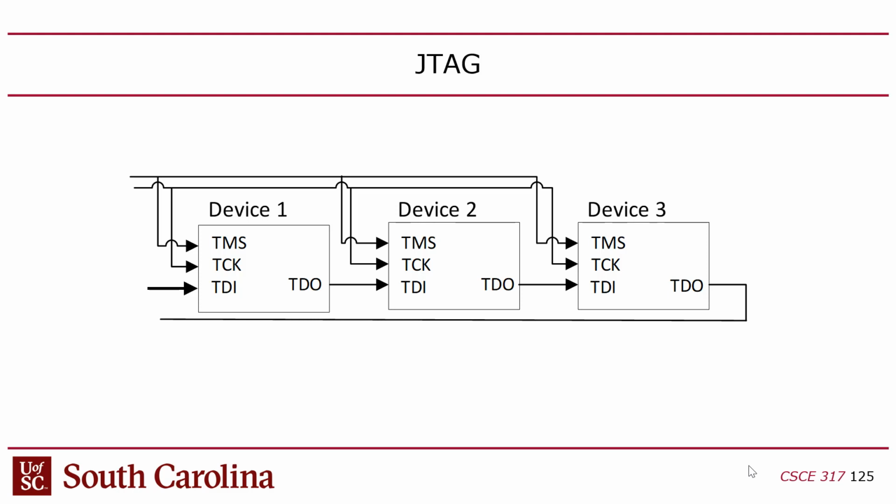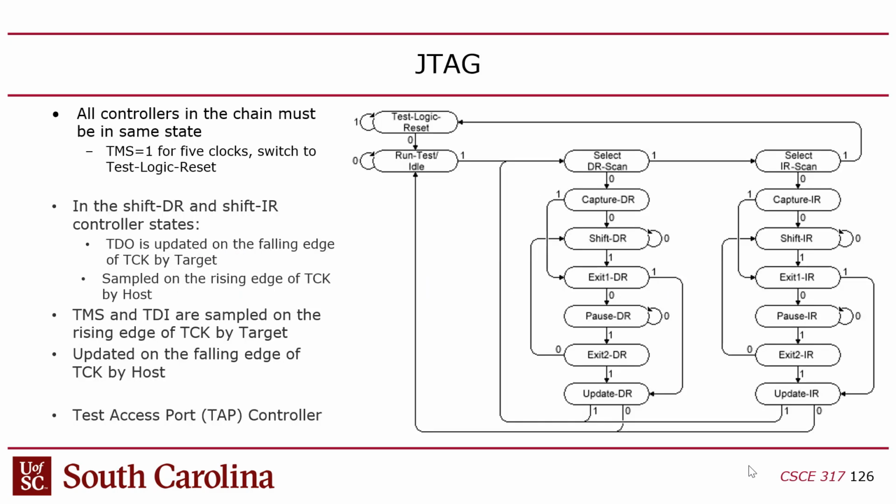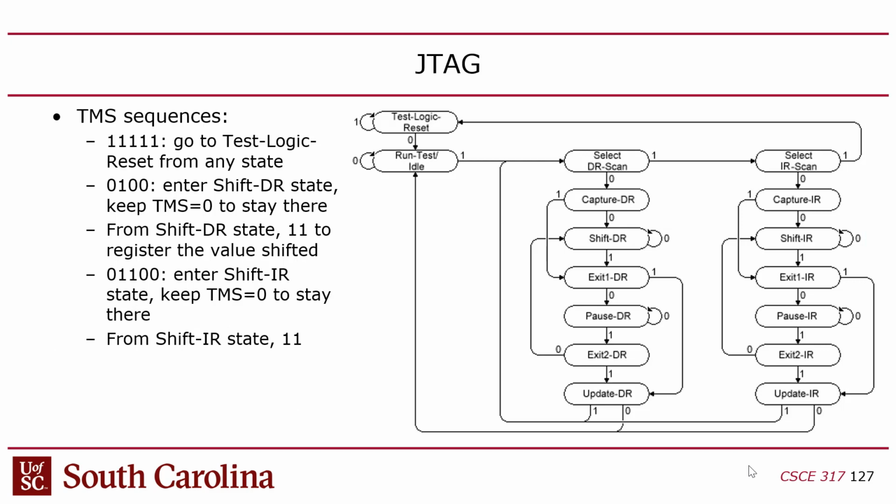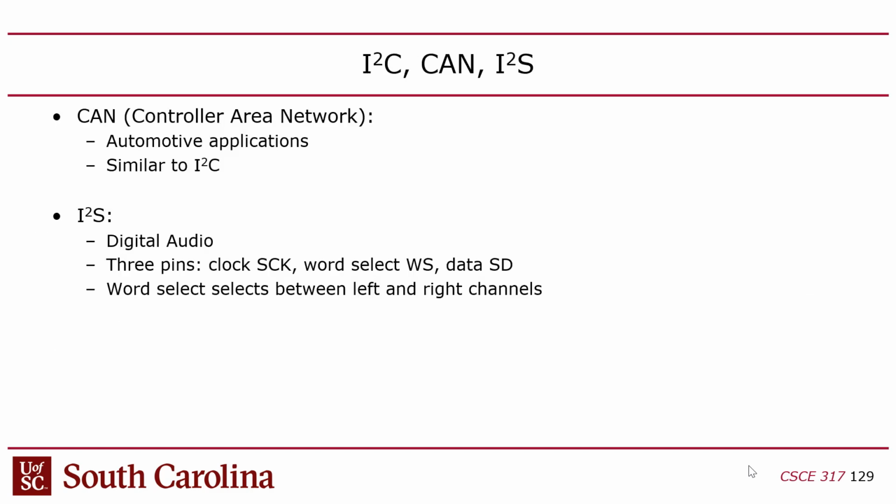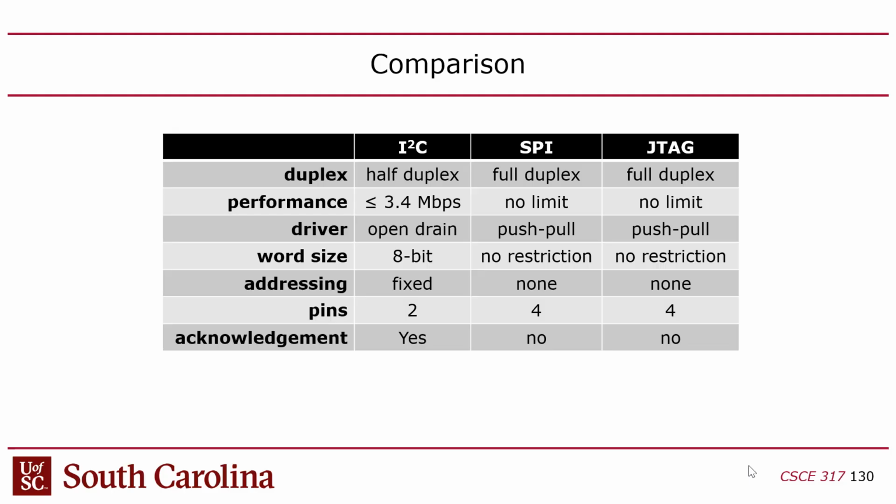There's millions and millions of bits that I have to configure, which is why when you program the FPGA, it takes a while. You have to sit there. It takes like, what, 10 seconds? Something like that when you program it? And that's the reason why, because all the bits are serial. It's a big shift register. And it runs at like a megahertz, so it's pretty slow. Okay, and that's basically it. Any questions about that?